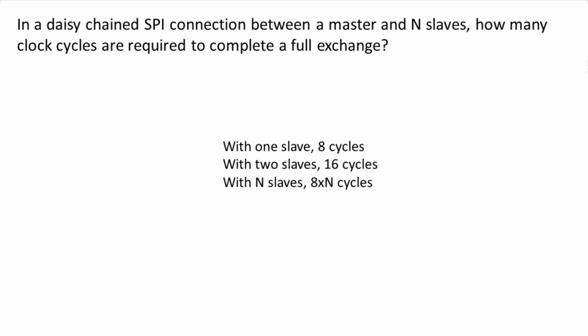So the answer is 100%, right? Because you can keep the slave select high and then just keep issuing transactions. Now the problem here is that you still have to send the address and the data. So if you did that, you'd still have the address, but you would be using 100% of the bandwidth.